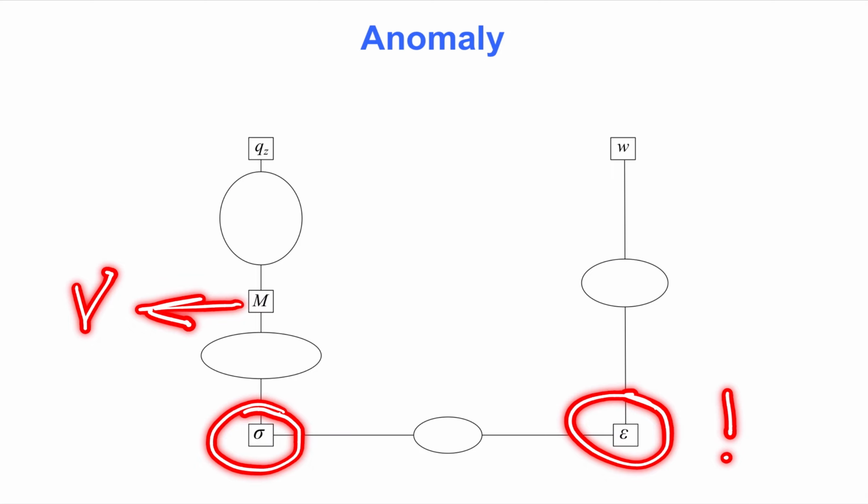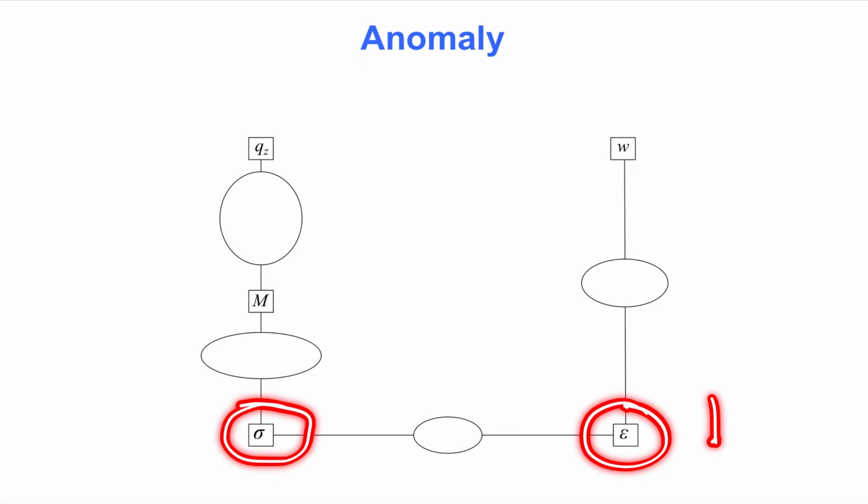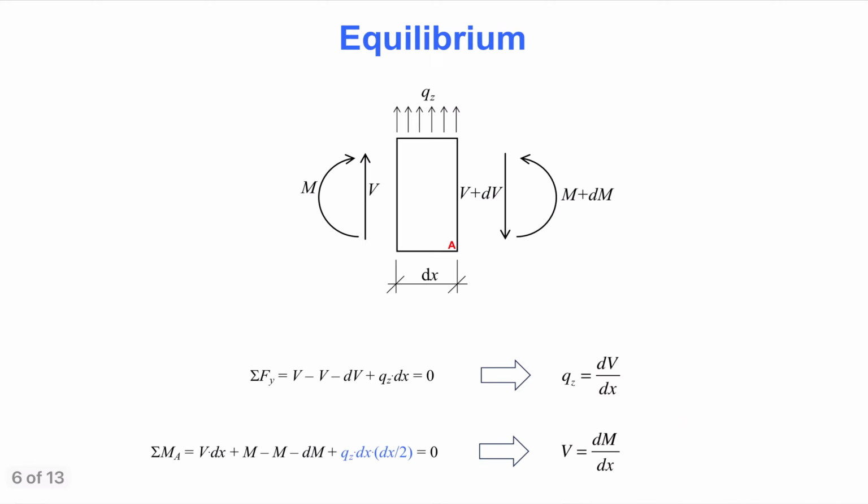The formulation of the boundary value problem omits shear stress, but a shear force must be present. The anomaly is solved by adding equilibrium considerations that are outside the formulation of the boundary value problem, in order to recover the shear force. Also, in another short course on cross-section analysis, we will add equilibrium considerations in order to recover the shear stress. In summary, we formulate the boundary value problem for beam bending in terms of axial stress. Then, later, we introduce additional equilibrium equations to recover the shear force and shear stress. The next slide presents one such instance.